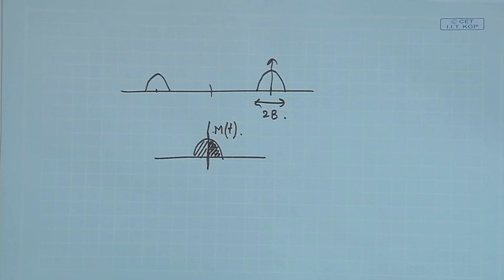So, if we can employ something where we do not have to transmit both the bands, then I can save some bandwidth, because this is the band it will be occupying in the channel. So, 2B is lost. If I can reduce it to B, the other B I can use to transmit another signal, and if all the signals are of B bandwidth, then I can transmit double the number of signals utilizing the same band, right.